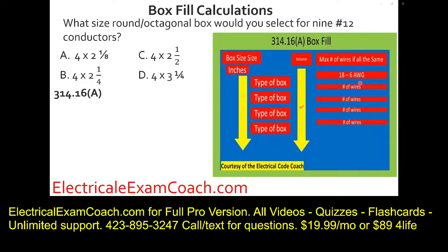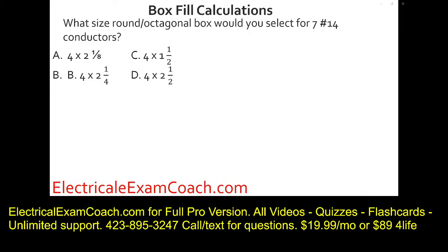We want to stay in the round octagonal. We find our conductors, we find the one that fits it, we slide over and double check ourselves, and we're going to select A. Great job! What size round octagonal box would you select for 7 14-gauge conductors?